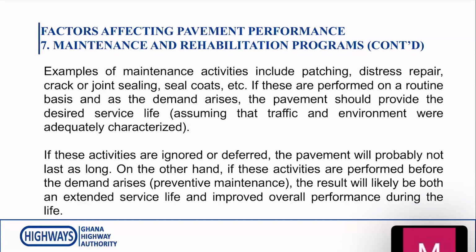If these activities are ignored or deferred, the pavement will probably not last long. But on the other hand, if these activities are performed before the demand arises, which is preventive maintenance, the result will likely be both an extended service life and improved overall performance during the life of the pavement.